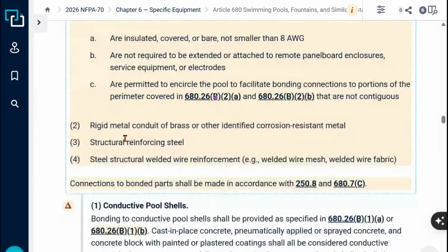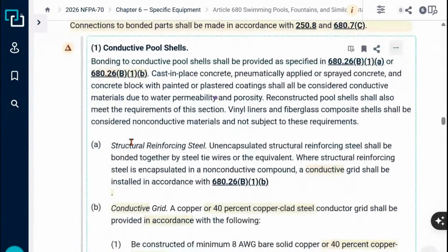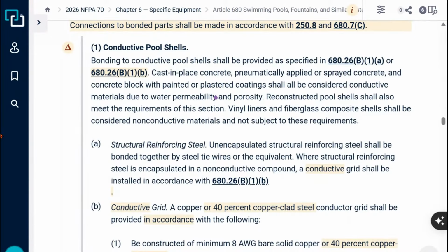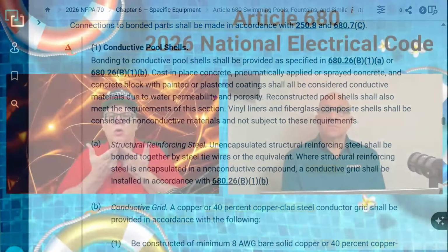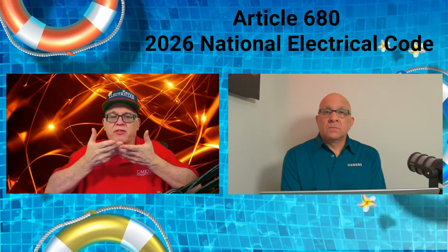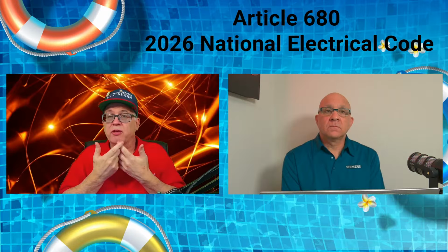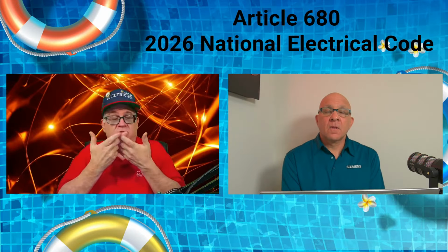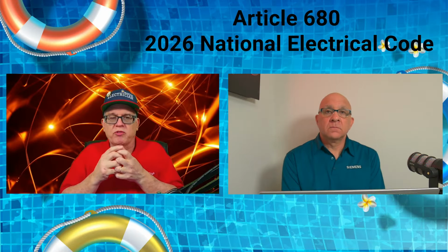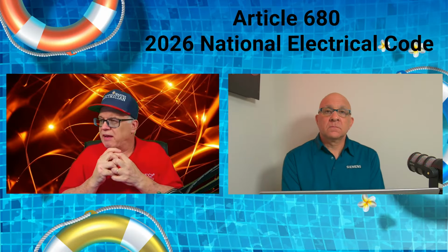the conductive pool shell. All right. So conductive pool shell. This is the portion, if you have a pool, for example, this is where the pool sits, right? So this is a conductive pool shell. I can have rebar encased in concrete. I could have block. Block is porous, even if it's painted, it's still porous, absorbs moisture. All of those are conductive pool shells that you could have.